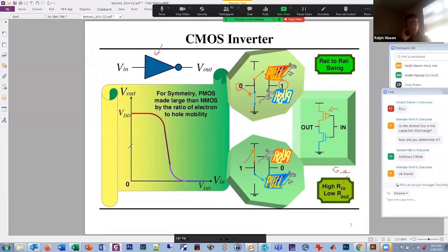And we can draw this DC transfer curve, which shows Vin on the bottom and Vout on the top, right? I don't know if you might have done transfer curves when you took electronics 1, but all this is saying is that when you're down here, Vin is low. That was the situation here. Vout is at VDD, all the way to VDD.